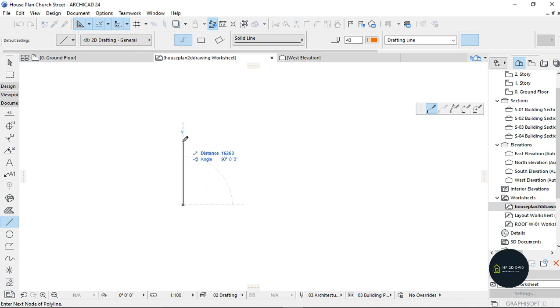And what I want to do next is, I already have this on my phone, so I'm just going to be drawing it out. So it is 22. I'm going to press tab on my keyboard so it can go to the angle. I'm going to write 22 degrees, spacebar, and 41 minutes. Once I'm done, I'm going to press minus on my keyboard. Automatically it forms that line for me.